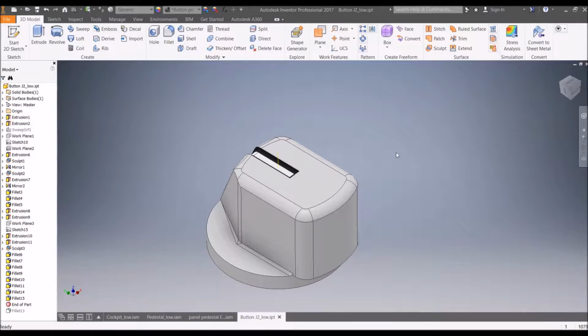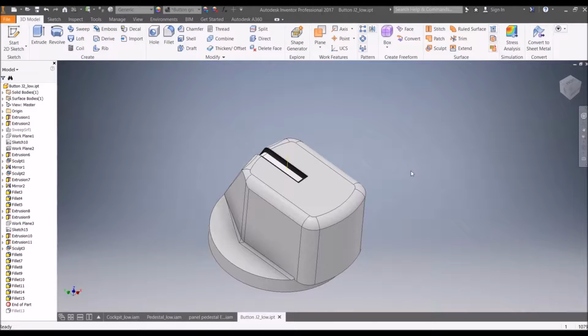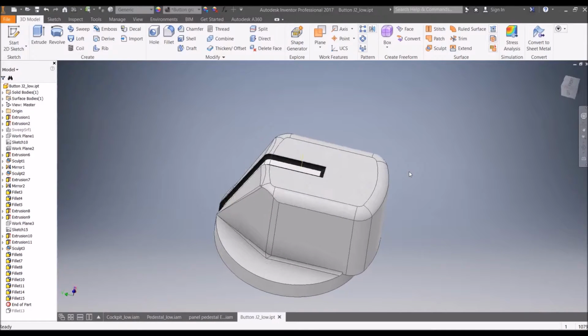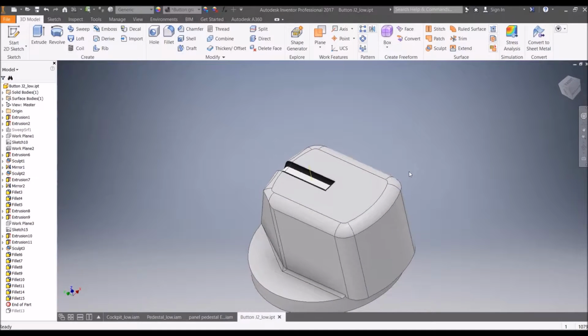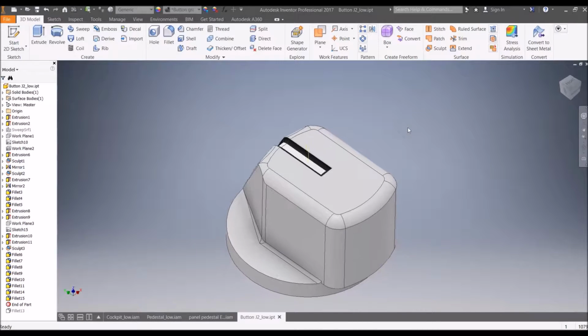What we do is we delete as much surface detail as possible. So anything that can be replaced by a texture, we're going to delete. Mostly those are fillets and some extrusions and things like that. And when we're done with that, we are going to delete some of the surfaces which are not visible.